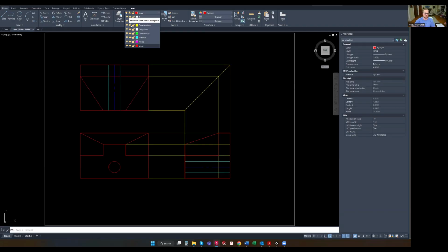So I would turn those off in that case just to be safe. But freezing works too, and the machine will not then cut those lines and cut the dimensions in. So that was for reference. The dimensions were there. The CNC operator, whoever it was that was programming that machine, could verify for a fact that flat pattern did have accurate dimensions on it. Then they could go ahead and turn that layer off and cut the part.